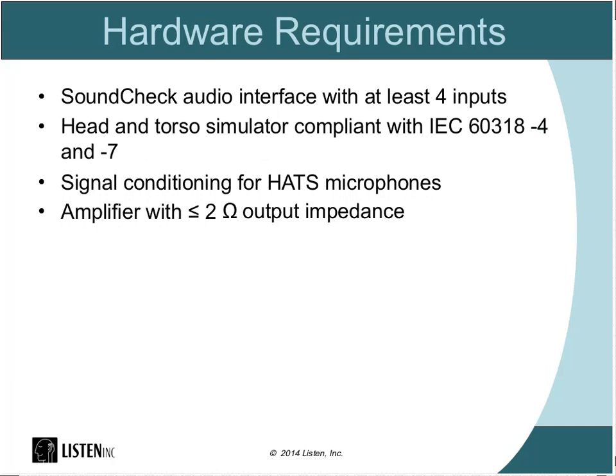On the hardware side, if you're going to be running the -2 portion of the standard, and you're going to be running the analog headphone sequence, you will need a SoundCheck audio interface with at least 4 inputs. I'll go over the reason for that in just a little bit, but that's the only sequence that needs that. If you're not going to be running the analog headphone, if you're just going to be running digital or testing the music player, then you can get away with just a 2 input device. So if you're doing the headphone portion, you need 4.